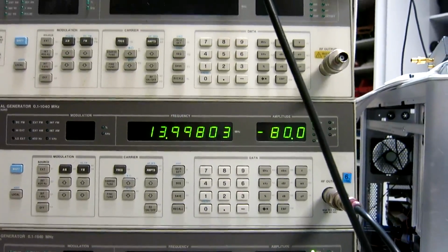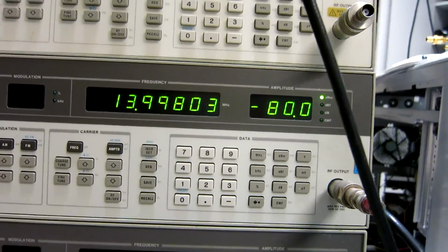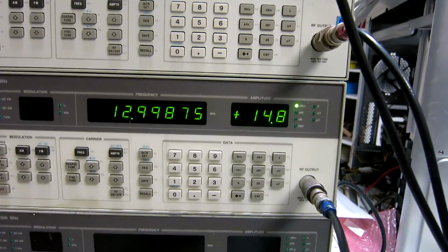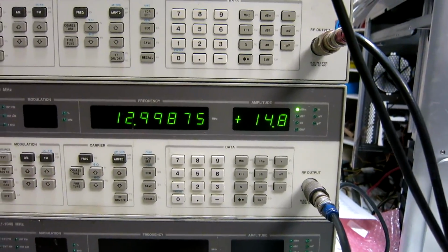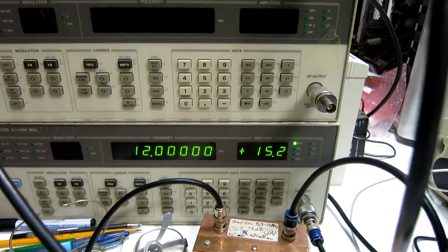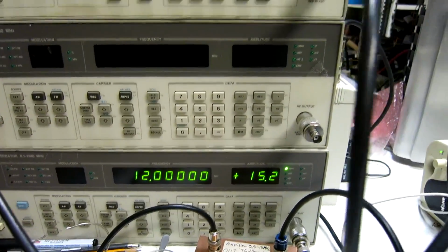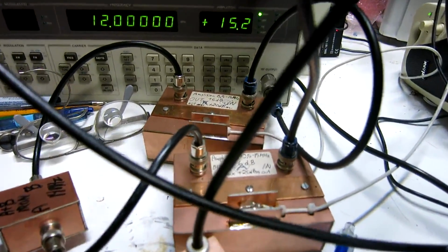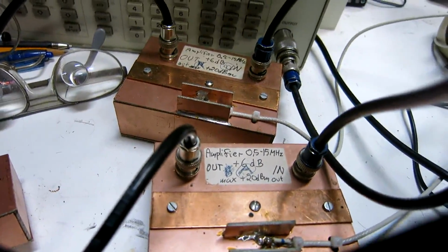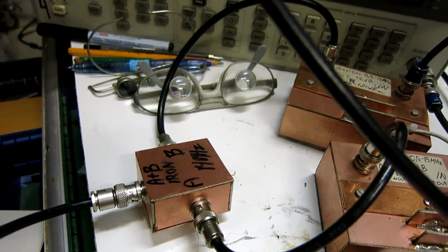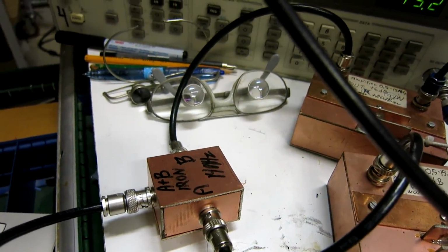So this is the signal I send into the directional coupler. Here is another generator which is set to maximum level or near maximum, and here is another one. They are set to provide the same signal level into the test objects. The signals from these generators are amplified by 6 dB in these amplifiers, and then combined in a 2-port combiner, hybrid combiner.